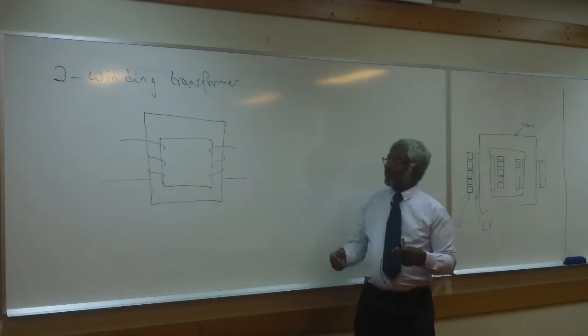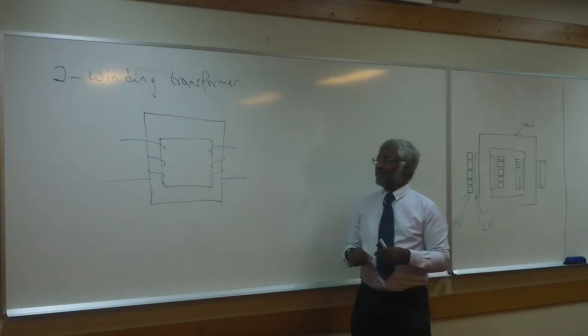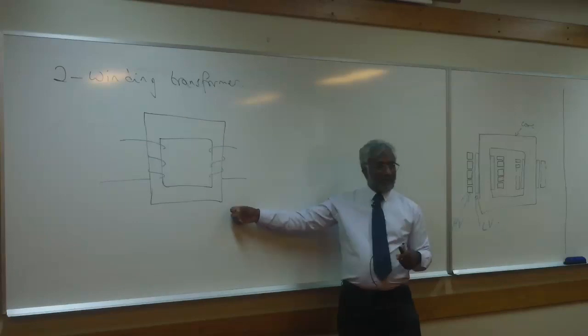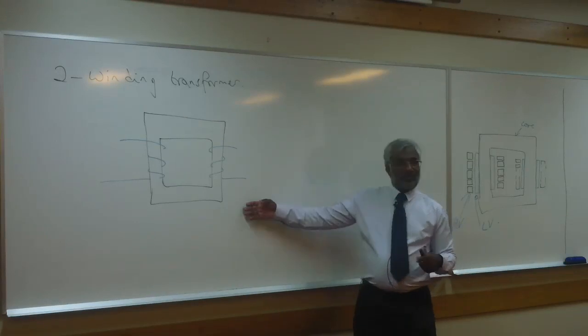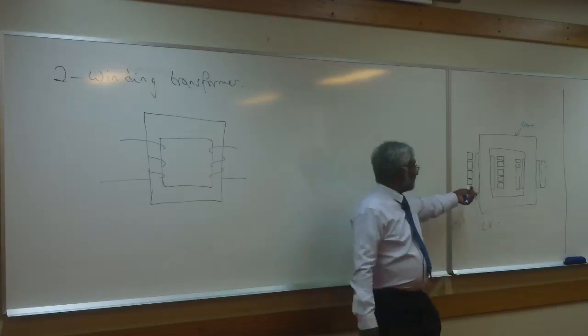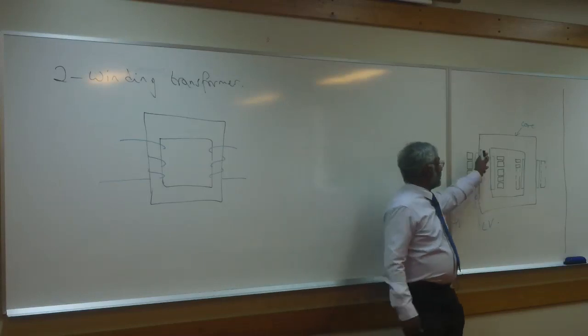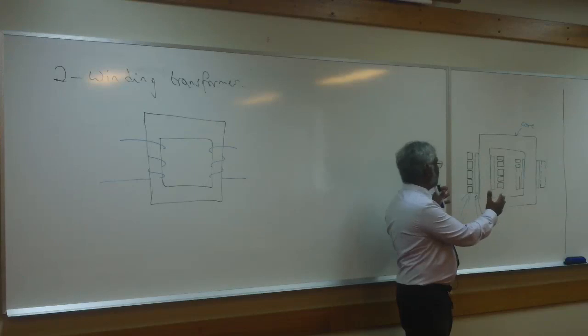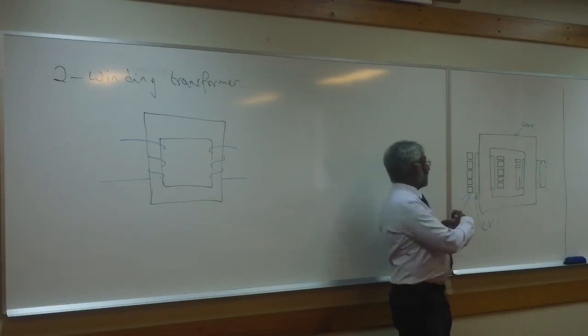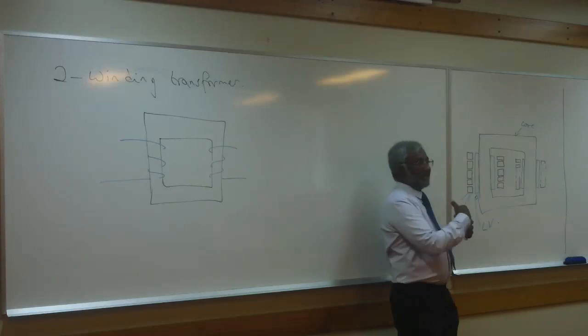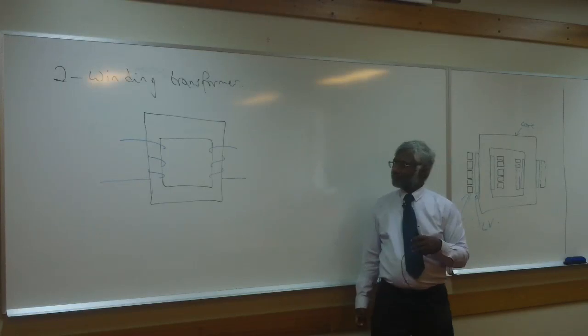For now, we'll focus on single phase with primary side, secondary side, but remember, this is not a normal way to construct transformers. That's more normal, where the low voltage and high voltage side sit on the same leg so that you get maximum coupling, magnetic coupling between them.